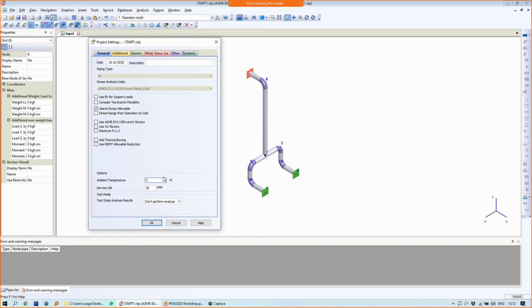My discussion here is when you have -20, because you can't do the fabrication at -20. When you're talking about Russia, because I also work on a lot of projects on Sakhalin Island, the platform where this pipework is getting installed, all the structure and the empty pipework, sees the same ambient. So the question for me was, in your analysis, are you setting this temperature to low temperature because the fabrication will be at -20?